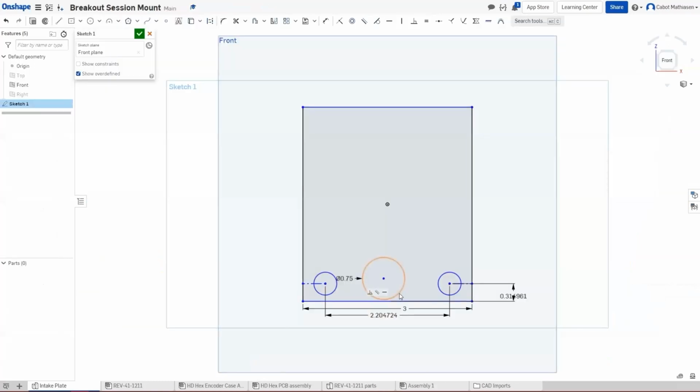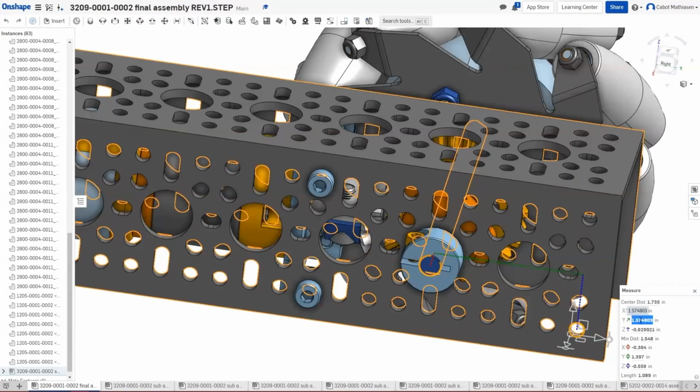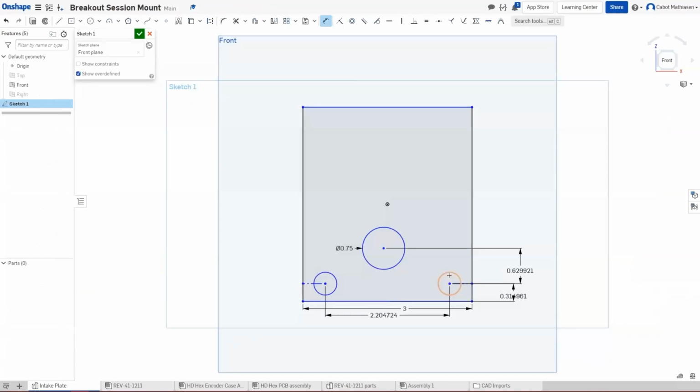So this is like 0.6299. So I will click on the center of each of these circles because that's where I dimensioned from. And see it copied in a negative, just take off the negative. So here will be the horizontal distance, which will be 1.57. So that's how far to the left it will be. Again, click on the center points. Make sure it's not at the diagonal or to the right. It depends how it's positioned, how it dimensions it.